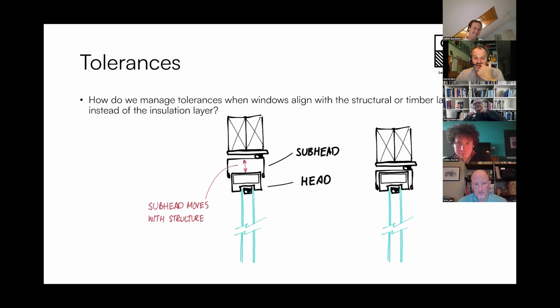Yeah, for me as a bricklayer, this was really something I've never seen when I crossed the border, because the bricklayer actually puts the wooden frame onto the last layer of the stones, and then just holds onto it. Maybe there's a short temporary fixation with a piece of wood, and then he just puts the bricks to it, over it, and that's it. There's a little concrete beam on top, and then the window always fits because he just uses his stones as a frame. It's a very lazy way of building, but of course you eliminate all the tolerances later on, because when the guy with the window opening comes, it fits for sure. Yeah.